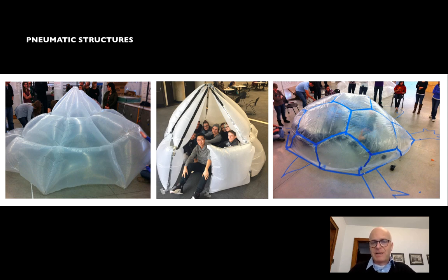There'll be arches obviously in more than one direction, but the fundamental principle that we want to think about is to think about pneumatic structures as basically cable structures or arch structures where the logic is completely inverted, so that instead of thinking about hanging a cable or supporting an arch, we're actually going to think about a cable that we're putting energy into, we're putting a load into, just like in the dead weight cable structures that we looked at a few minutes ago. Here we're doing the exact opposite.